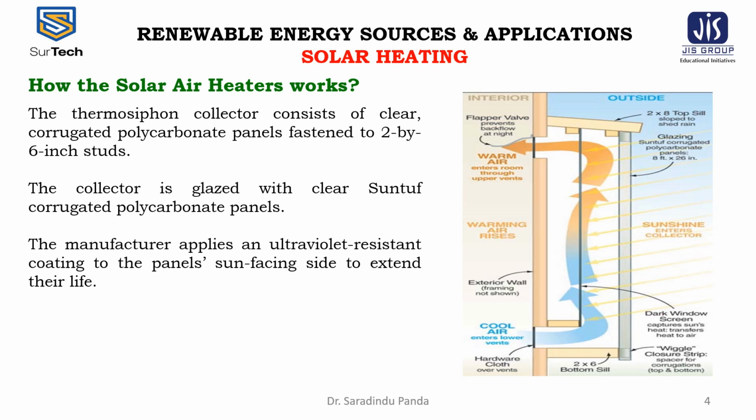In altering the collector's design, make sure you don't violate these guidelines. Number 1, the collector's depth should be at least 1 by 15 its height. The absorber must offer low resistance to airflow.